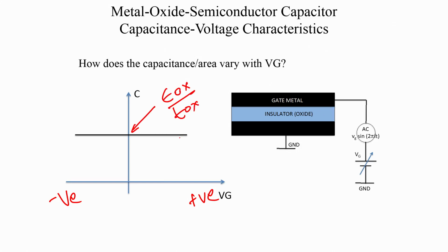Okay. Now, we can also try to vary the frequency of the AC signal, we can try to vary the speed at which we sweep, etc. But ideally, for an ideal capacitor, all this should not make any difference. You can measure the capacitance at any frequency and you should see the same behavior. But of course, in reality it is not going to be so, because every capacitor has also got, say, a resistor in parallel, etc. So, there are many leakage mechanisms, etc., which is not going to allow you to see this response. But let us just talk about the ideal case for now.